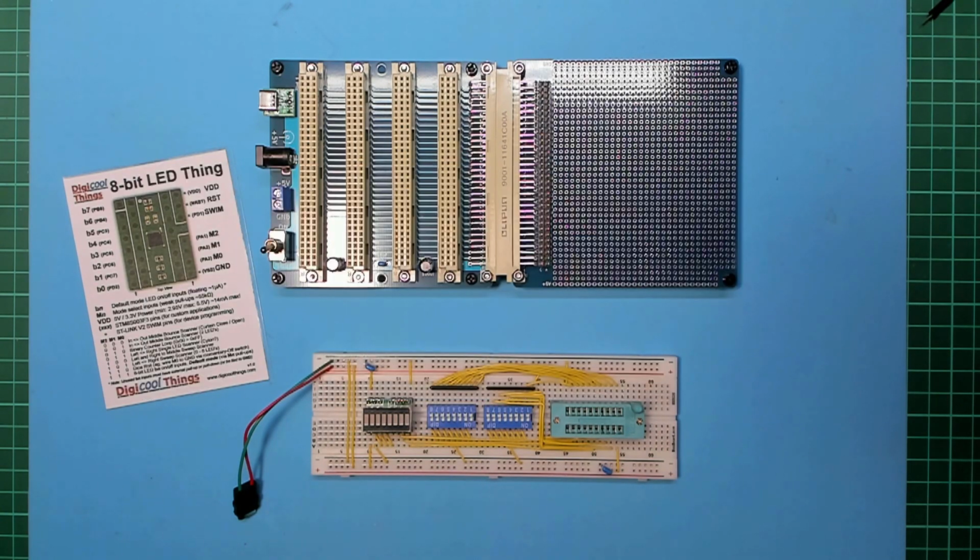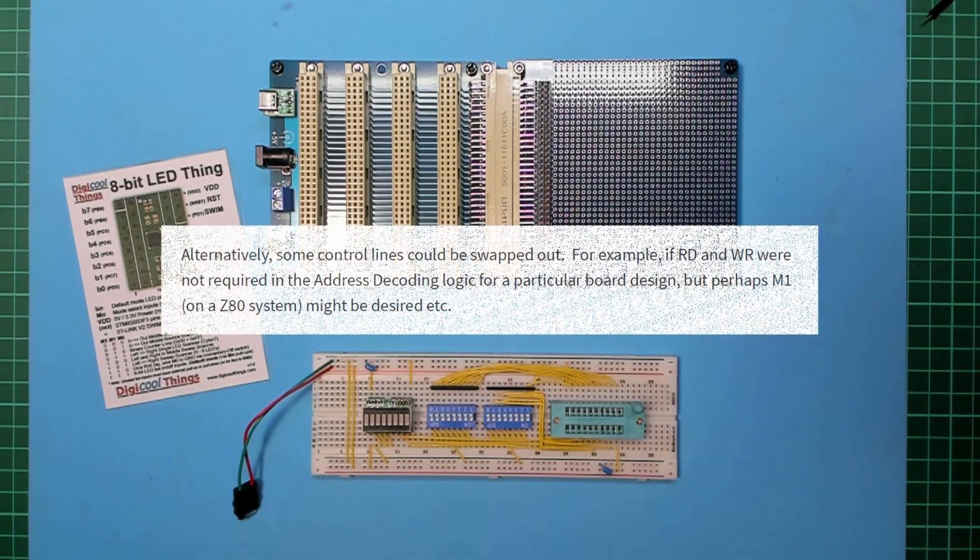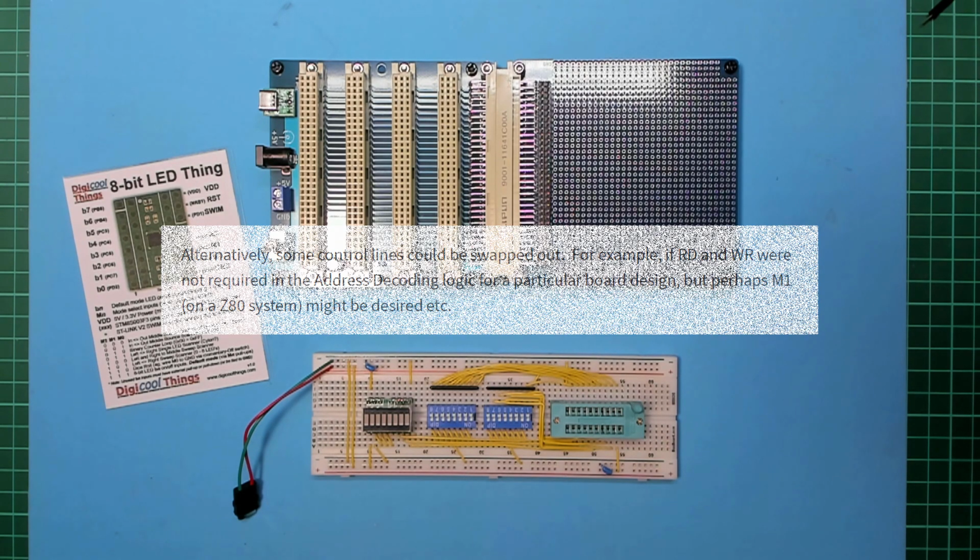Where this still isn't sufficient for the required decoding, then an individual card design could, of course, still implement some supplemental gates to complete the glue logic, while still maintaining a minimal chip count and still retaining some PLD-based address map flexibility. Alternatively, some control lines could be swapped out. For example, if read and write were not required in the address decoding logic for a particular board design, but perhaps M1 on a Z80 system might be desired.